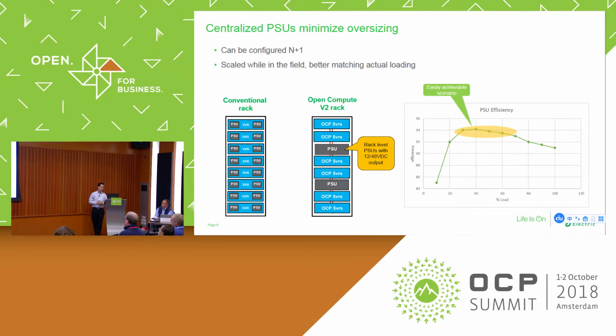And the other beauty of this architecture is that the power shelf unit can easily be expanded, since most of them are modularized designs. If you are doing three-phase, you can put down 2+1, or 5+1, or N+N, like 3+3 or 6+6. So you have some flexibility to adjust the power supply unit, or you can change to a bigger shelf or put more shelves in the rack, so your server can run at the best efficiency across the whole rack.